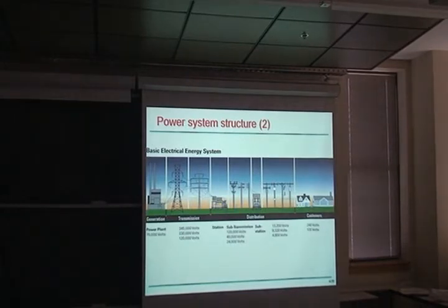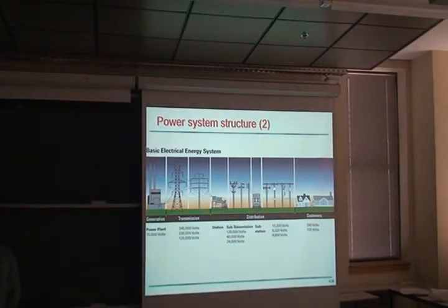Did you say that was a less common method of electricity transportation? Yeah, it is. Of all the transmission across the US, there's probably 5 or 6 DC in the thousands that exist in the US. Because it's a really sort of a niche market. It only becomes economic when you're carrying a lot of power a long distance. There's a new technology that has come available in recent years, and it's starting to find more applications.